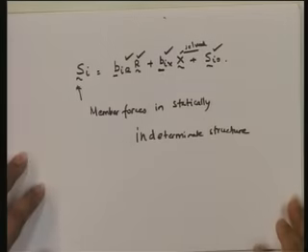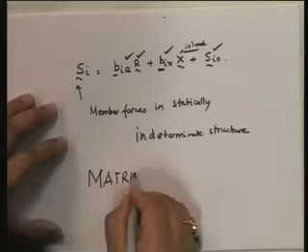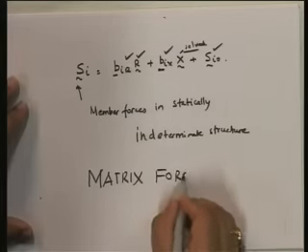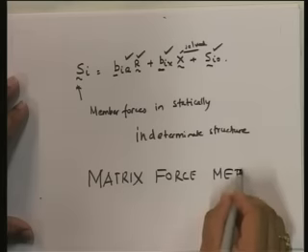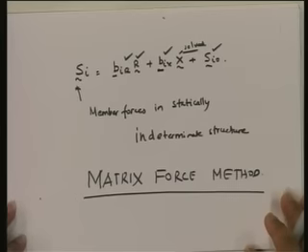Therefore, you see the beauty of this is known as the matrix force method. The beauty of the matrix approach is that the force method becomes a part of the overall flexibility approach. We are not having to derive it separately. The redundant force is just treated as another additional load, which of course we don't know.